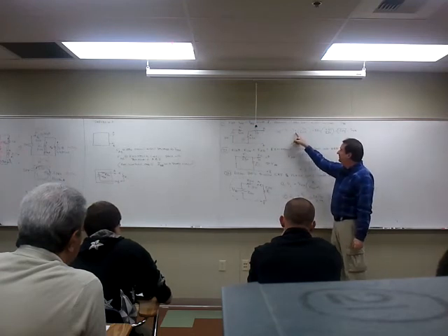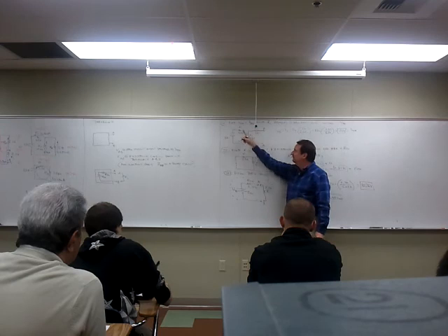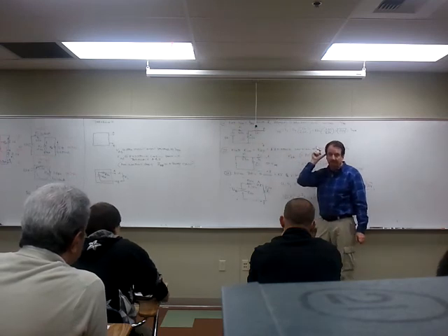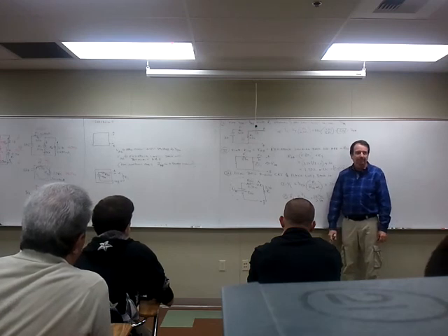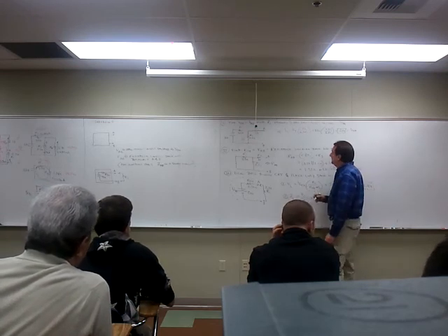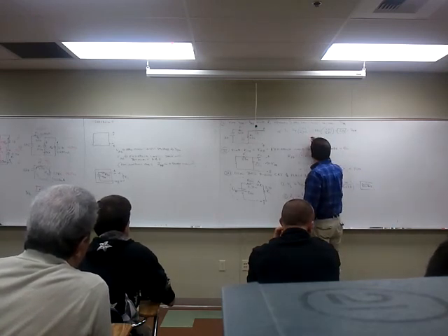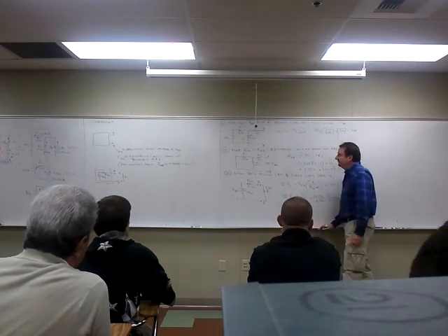So it's the total voltage times the ratio of this resistor over the sum of the resistors is how the voltage divider equation works. Remember, the current divider was the opposite resistor on the top? The voltage divider is the same resistor on the top. So it's R2 over R1 plus R2 times the total. We came out with 20 volts. That's our Thevenin.